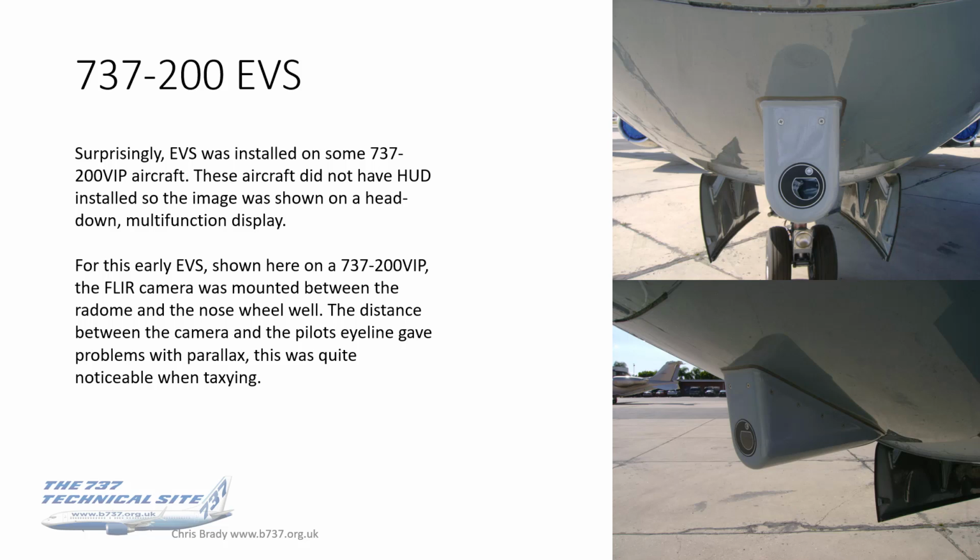Now, going back to the 737-200, this actually. There were some 737-200 VIP aircraft, which was the forerunner of the BBJ, that had EVS installed. Now they didn't have a HUD, so it was all head down displayed on the multifunction display. The camera was actually mounted between the radome and the nose wheel well, as you can see in these photos.